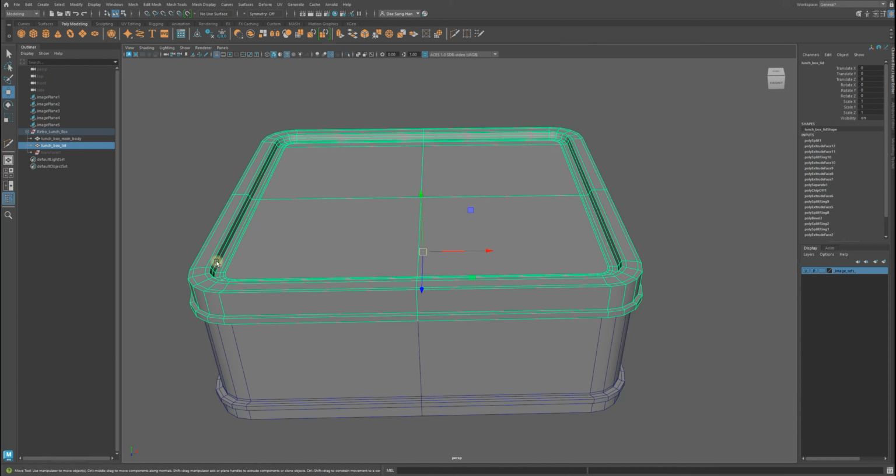Red is your X axis, this way, like that. So symmetry is off. Click here. I'm going to do object X axis. There's a difference between world and object, but to be safe, object X. The object's X axis, right?